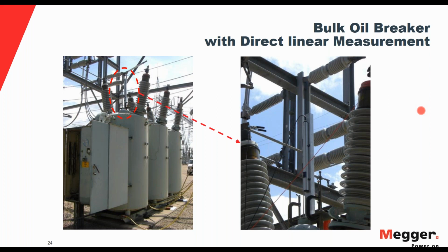One model is an SF6 live tank circuit breaker. One model is Dead Tank. Another model is GIS. All of them might not have the same mechanism. You might have different types of mechanisms. So for that, you need to know your mechanism and then find out where. And after that, you can obtain a transducer that can fit or mount on that mounting area.